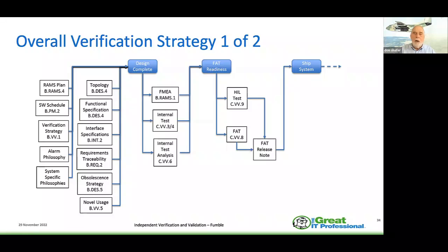Fire alarm? What it is that on a drilling system, a production system, an offshore system, even an onshore system, every one of the subsystems has a set of alarms that flash lights and sound horns if there's something wrong. Well, that's okay if you've got one system. When we're integrating these, we may have anywhere from 20 to 50 systems, everything from a fire detection system to a gas detection system to what's on the different top drives or the crown block. Where are the sensors? So I have to have those around. I have to have system-specific philosophies. How do I manage these? Because I've got one or two people who are running all these, and they're doing the drilling. So how do I make sure that happens?